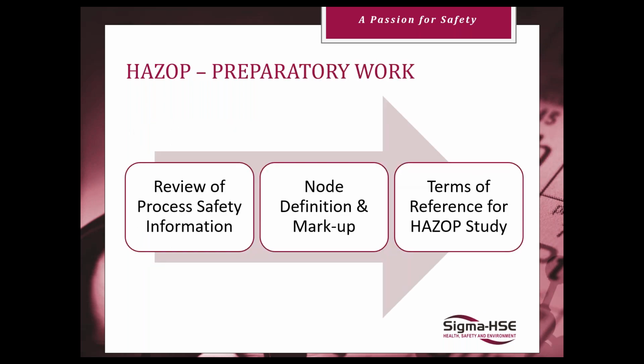All right. So yeah, the review of the PSI, node definition and markup, terms of reference for the HAZOP study. If it's a new team not familiar with the process, you want to make sure everyone involved has a basic understanding, not only of what you're doing, but the terminology and the guideposts to make sure you're getting the most value out of your study.